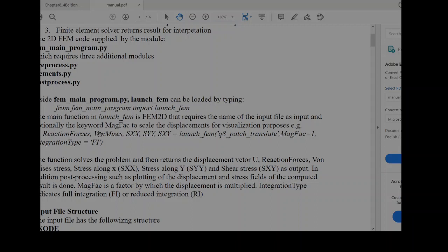Well, no, sorry, we have spoken about full integration and reduced integration. Full integration is when I use the minimum number of Gauss coordinate points to fully integrate an undistorted element. Okay, and reduced integration is if I use one less. That's essentially what that boils down to. So these are the options that we have, FI or RI for that one. We haven't looked at the implication of reduced integration, but we have spoken about it.